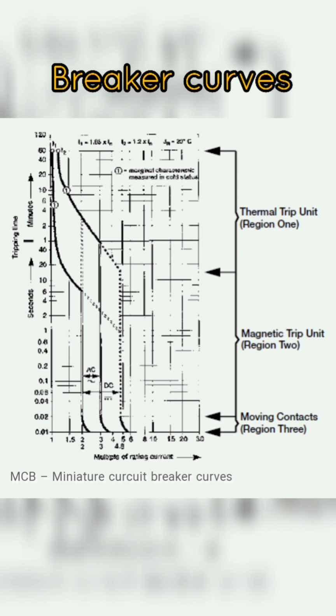Next you would trace the vertical 30A line up until it intersects the red portion of the breaker thermal curve. If you follow the horizontal lines, on both sides of the red curve, to the left you will see that the breaker can trip as fast as 2 seconds and no slower than 1 minute.